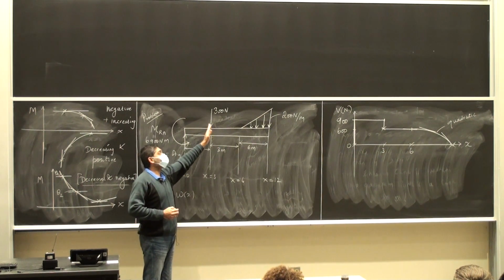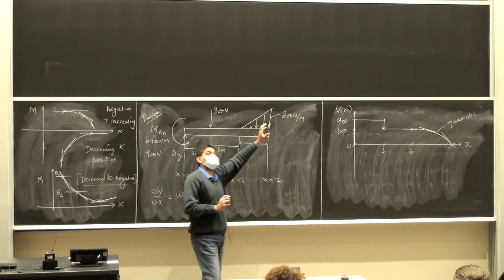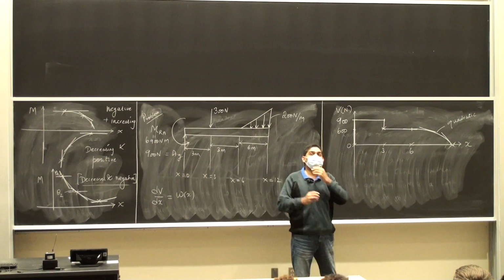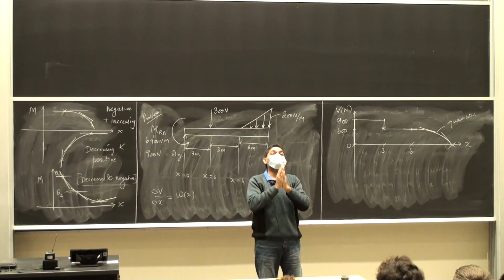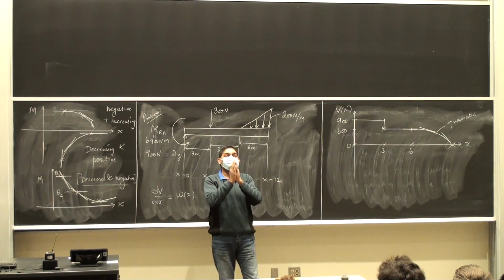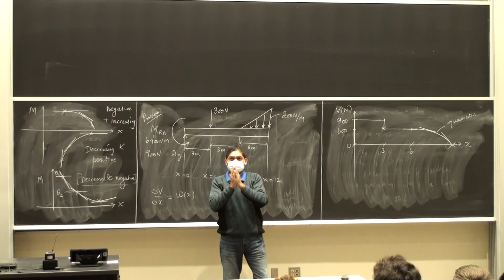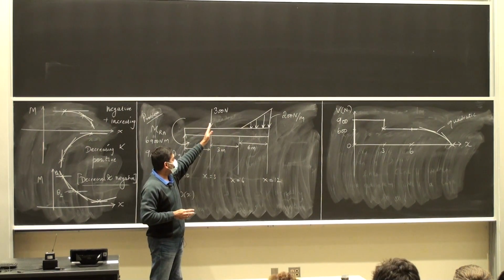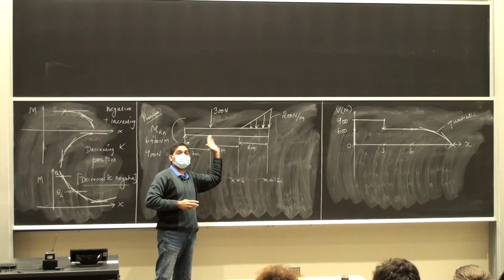Then I come to this guy. I'm seeing that it's pointing down, which means I have to decrease by that amount from where I was. So it takes me from 900 to 300, pushing me down. Singularity taking place in the free body diagram, concentrated force. Then I trundle along from here to there because there is nothing taking place.